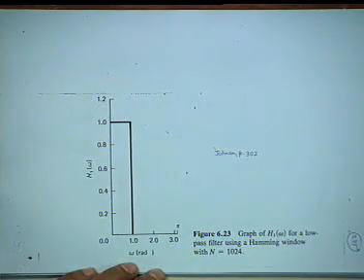Okay. So if you use sufficiently large length, what are the disadvantages of large length? One is hardware and the other is speed of processing, and therefore you shall have to bring an FFT hardware into it, alright, and then compute the convolution. See, yours is an input output case. You want to design a filter, it has an input, it has an output, it has an impulse response, and the impulse response is of length 1023. So you make an FFT of the input, an FFT of the impulse response, multiply the two and take the IFFT. This will speed up the process.